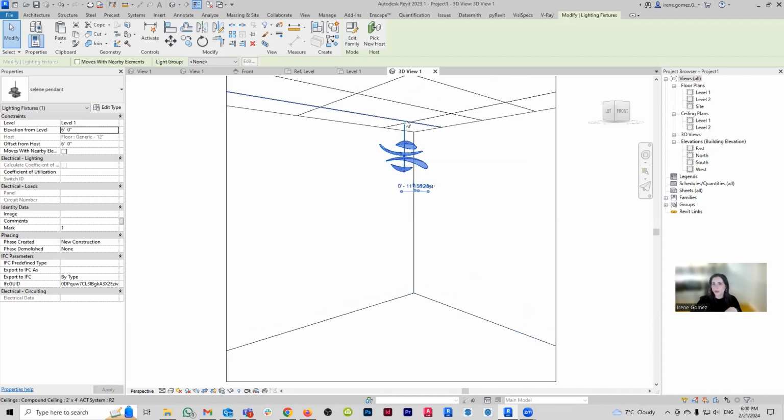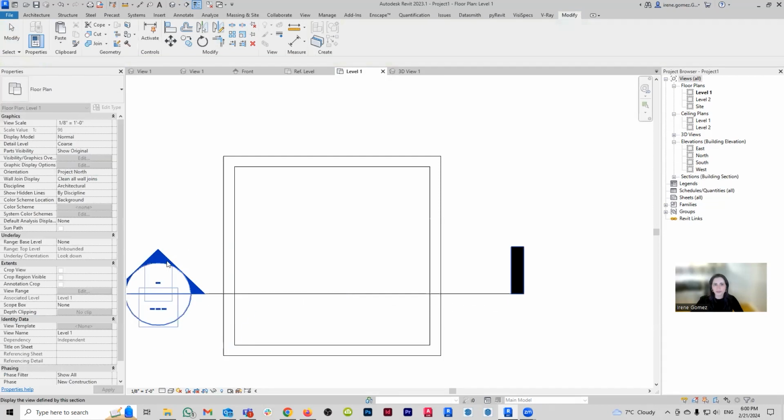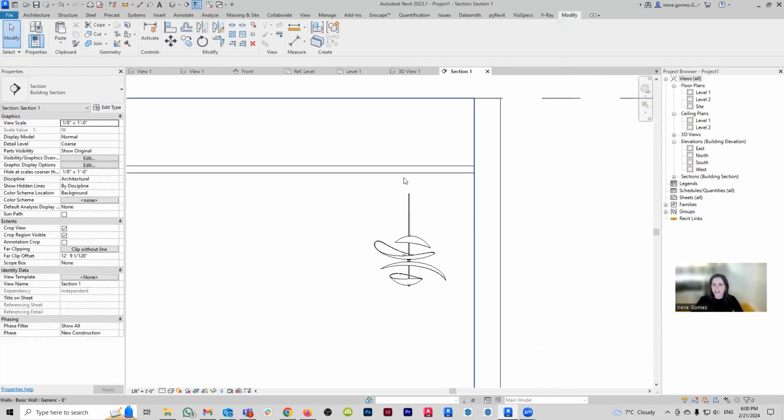Now, the other thing that I want to address is the height of the tube element. So one thing that you're going to notice is that I can't really change that value, but this looks kind of silly, like the lighting fixture is just floating in the air. It's even sillier if I create a section. So if I create a section here, and I open this, you can see that it's like someone is holding this light in place.